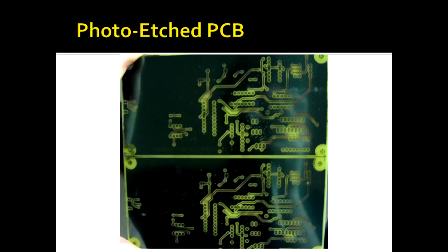So then I thought I'd make an even more feature-rich board. And because I'm thrifty, I decided to etch it myself, which was pretty much an epic failure. What happened was my transparency with the mask of the layout, which you shine the fluorescent light through, was slightly off the surface of the board, which had the effect of making the artwork out of focus.